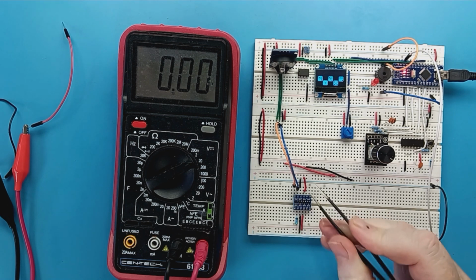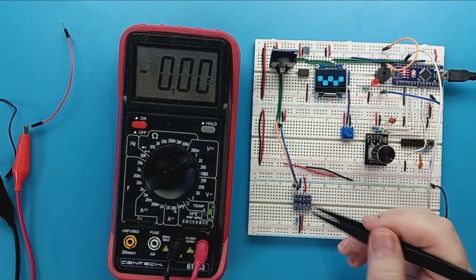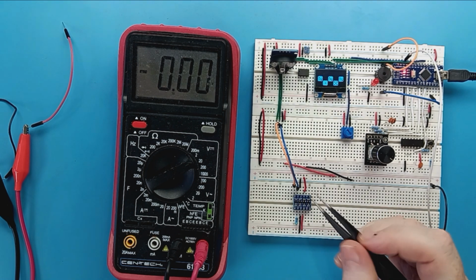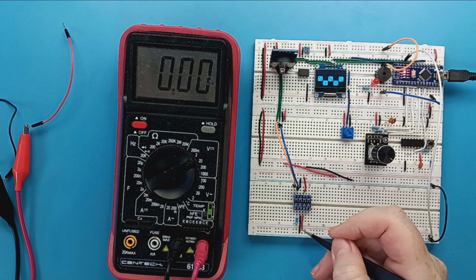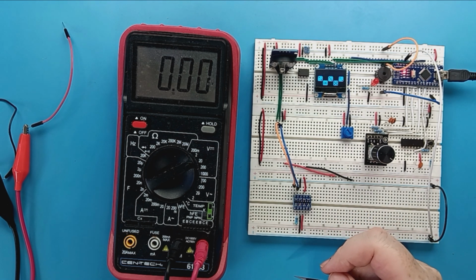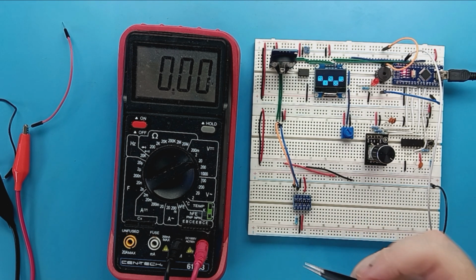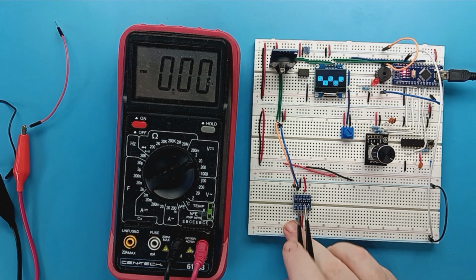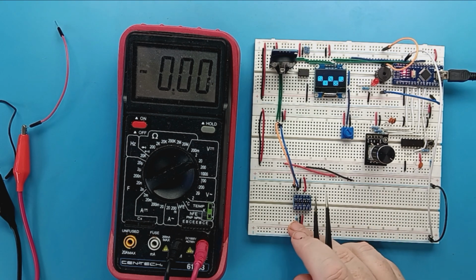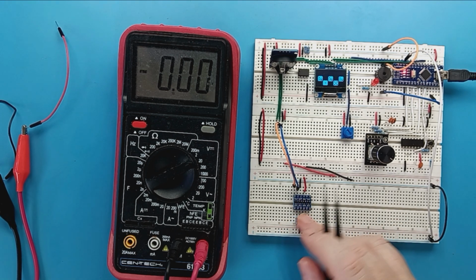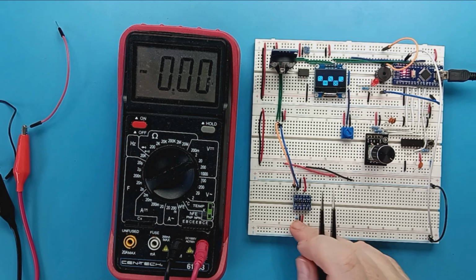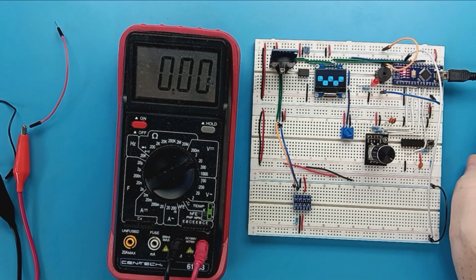Otherwise, the pin is going to try to float. We don't want that with the I2C interface. So we want to add pull-up resistors on this side of the logic converter, as well as having pull-up resistors on the 3.3 volt side. So I've just put in a single pull-up resistor. If we're doing a full interface, we would actually want pull-up resistors for both the clock line and the data line. But as I say, this is just a demonstration.